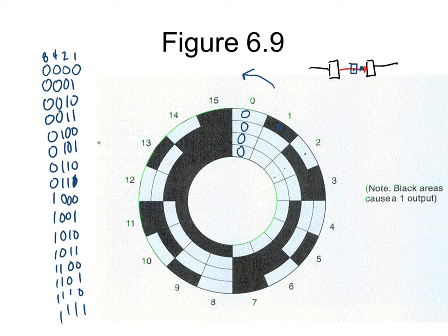Look at this. So I'd add a 1, and then I follow this line down right here. I got off. And this would be a 4. If I add these two together, that would give me a 5. So this is the binary equivalent to the decimal number 5. And notice what happens to the decimal weights. They just double every time. 1, 2, 4, 8. What would the next one be? 16, 32, 64. So this is what we would call a 4-track or a 4-channel absolute encoder.